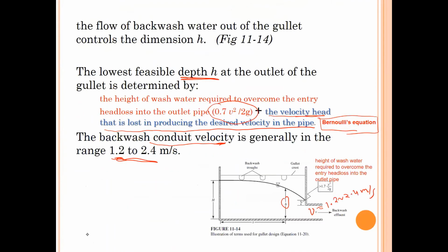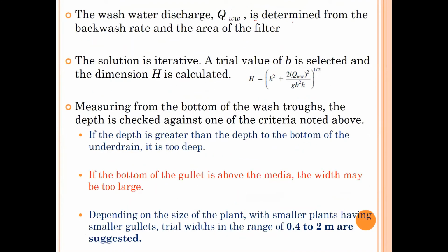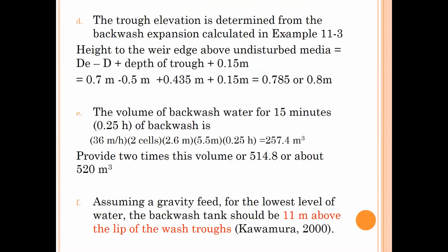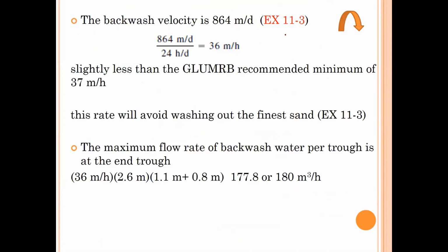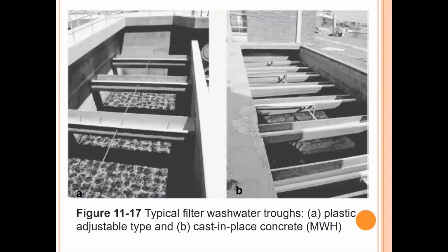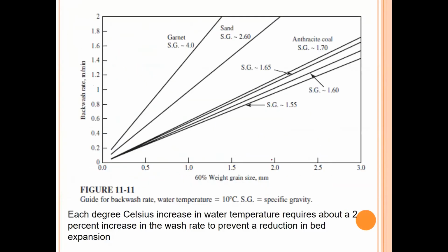This wash water discharge we already determined from the backwash rate and the area of the filter. Remember when we were solving the last problem, we calculated wash water discharge.